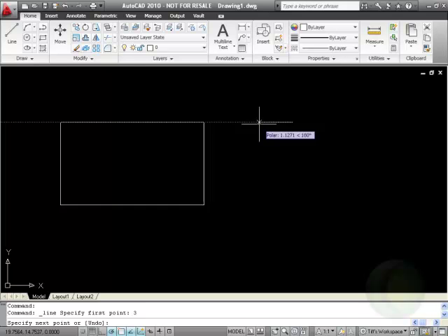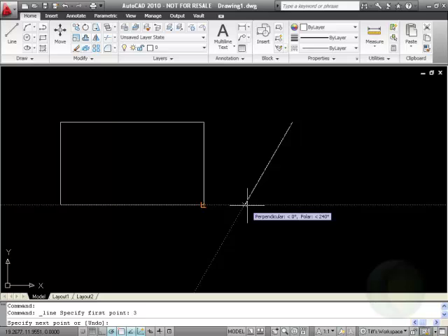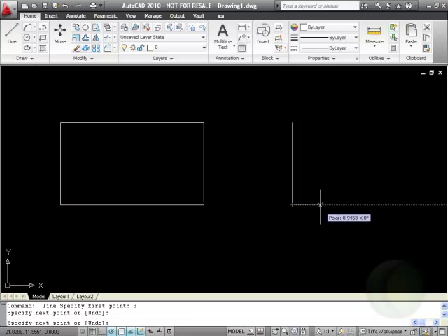Now let's start creating the side view. First, go up to the ribbon, select the line command, and then we hover over the end point. Not click, we hover to drag it across. That allows us to actually see the point being tracked, but we're not actually clicking on it to start the line there. Then we can still use our direct distance entry to put in the number 3 if we want it 3 units from our tracking point.